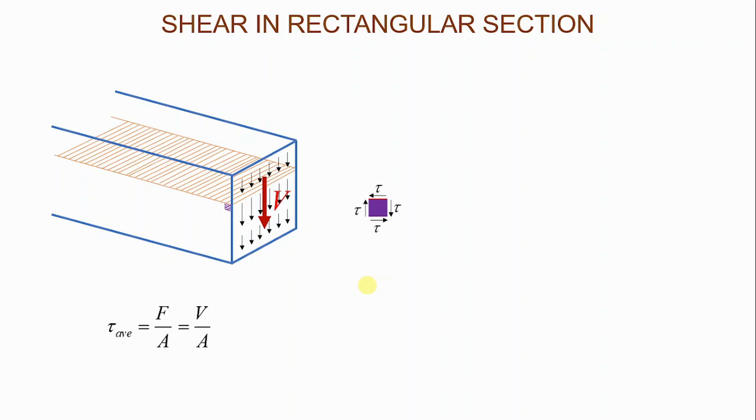But now we will look at it closely with equations so that you will know what are the steps that you need to take. Now, we're looking at the cross section of the beam. So what you see here is that area there. And of course, it's a rectangular cross section, therefore its neutral axis is right through the middle, because that's where the centroid is. And this neutral axis is the XX neutral axis, which is the one that is the stronger one against bending.